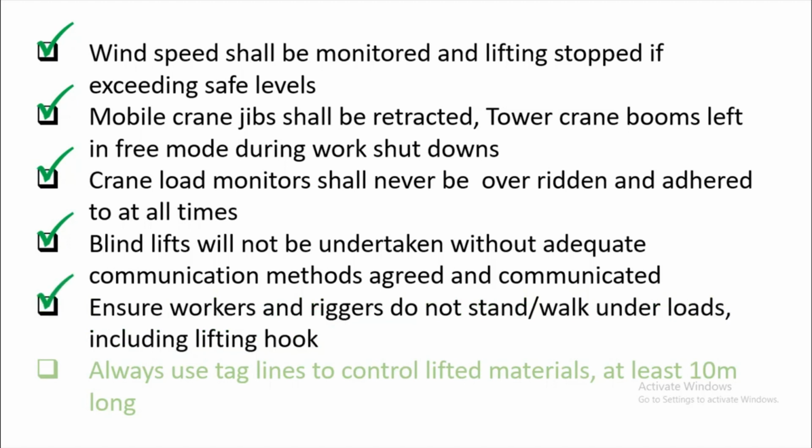Ensure workers and riggers do not stand or walk under loads, including lifting hooks. So when we have suspended loads, or if the crane is on standby mode, with the lifting suspended in the air, make sure that no workers are passing by below, or riggers standing by below that hook or that load.